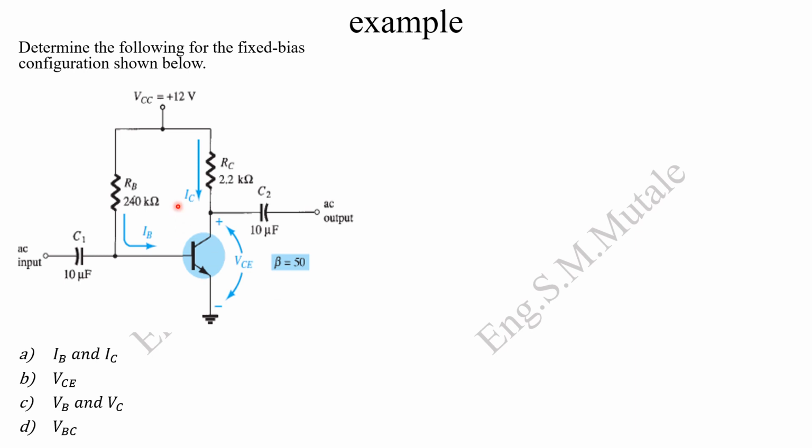We're going to start with this path. We can pick these routes going to the ground with the equation we had derived. Picking that route, we have that transistor with those terminals: the base, the emitter, and the collector. But our interest is just through the base and the emitter. With that route, you've got the resistor RB there, and there's a current passing through there, which we are calling IB.